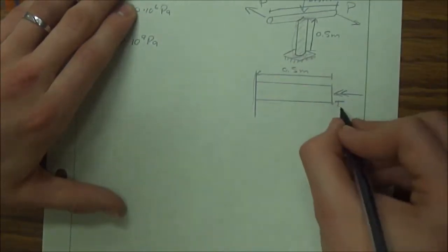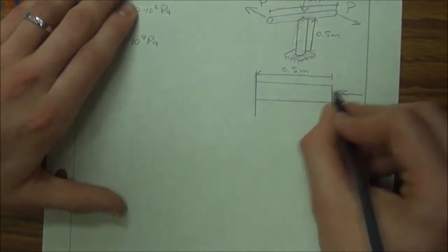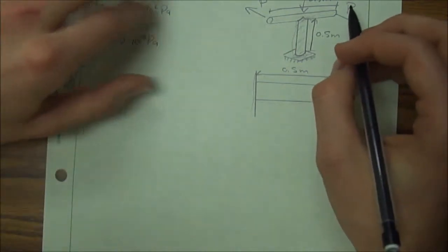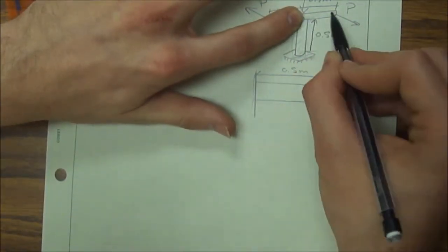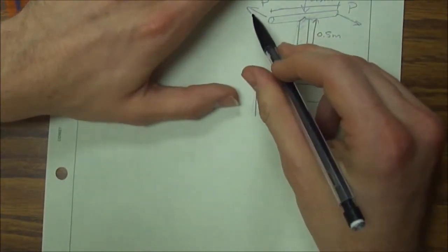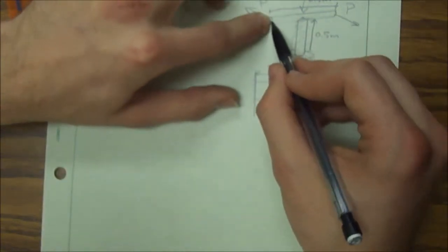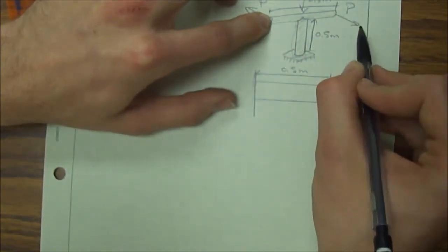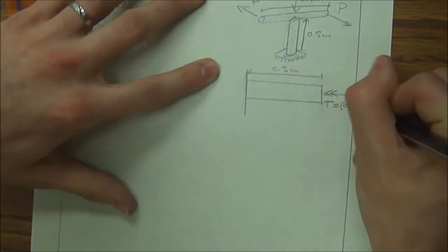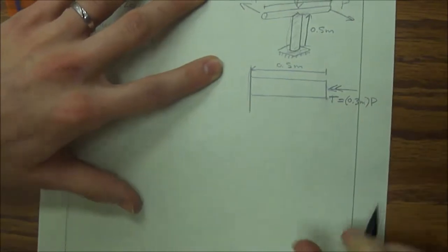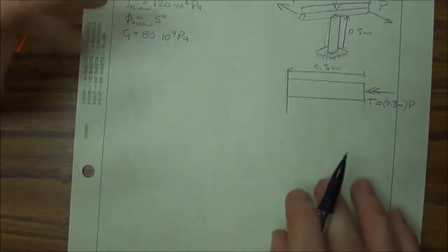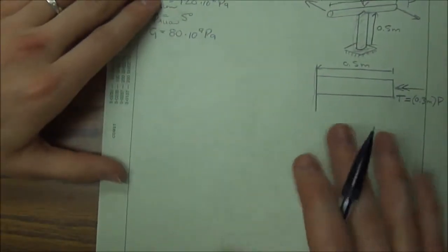This is an applied torque on the end, and it's equal to the load times the distance. If I look at just one side, half that distance is 0.15 meters times P, and then I multiply that times 2 because I have 2 of them. Or I can look at it just from one end and say it's 0.3 meters times P. It's going to give you the same answer either way. So whatever makes most sense to you, do that. So my torque is 0.3 meters times P. Notice that I keep my units in as I go. And P right now I'm going to keep unitless, just so that my answer presents me with the units. You'll see what I mean when I get to the end.